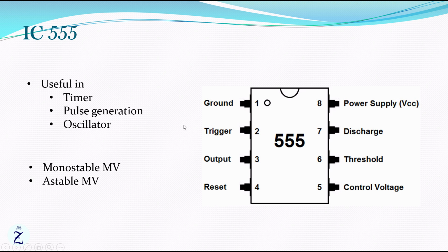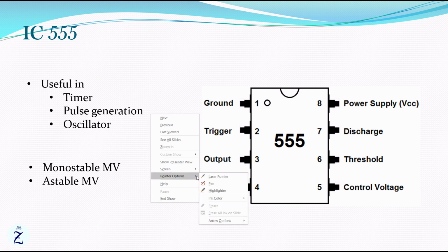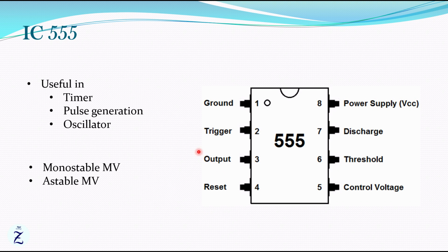Here we can see the pinout diagram of IC555. There are 8 pins available in IC555, each having some specific functions. They are ground, trigger, output, reset, control voltage, threshold, discharge, and power supply.